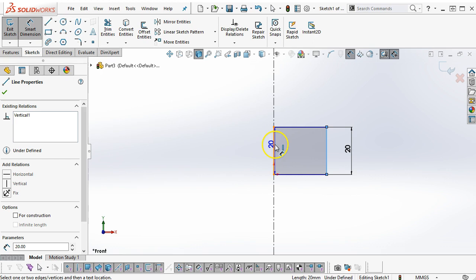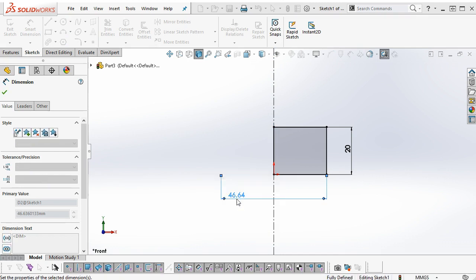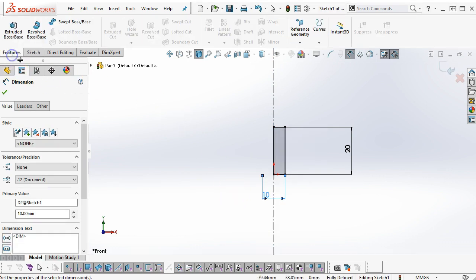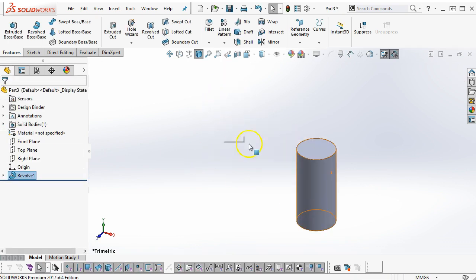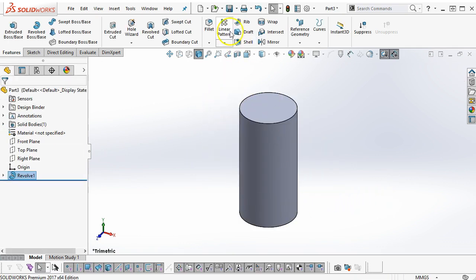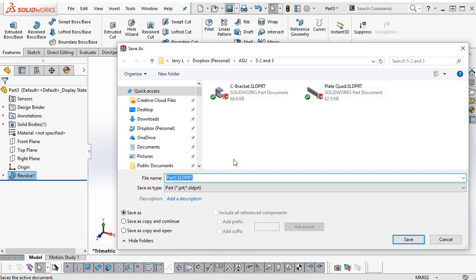If I pick an object and the center line, not two objects, because object and object will just give me that linear distance. If I pick the center line, then I have on the opposite side of the selection the diametral, and in between the radial. So I want to take advantage of that diametral, and now when I go in and revolve, we're at 360 degrees, that's my peg. So there are going to be times where geometry is going to be more convenient.